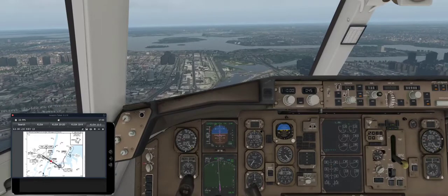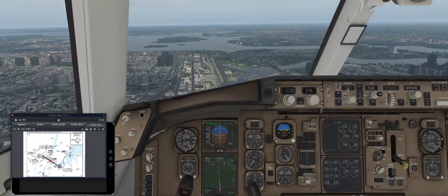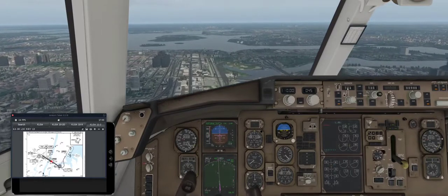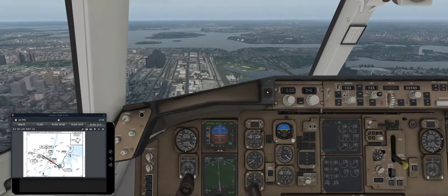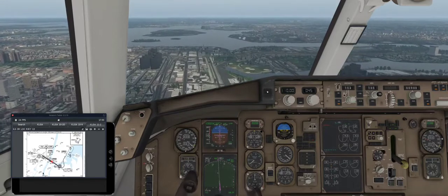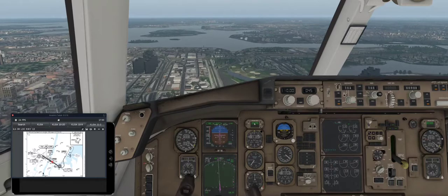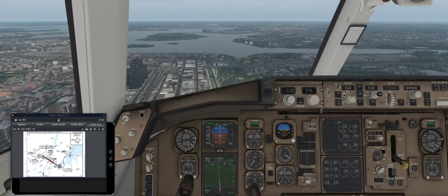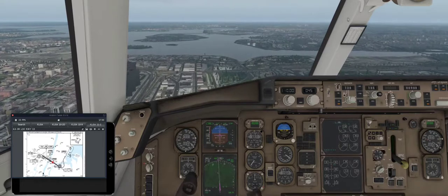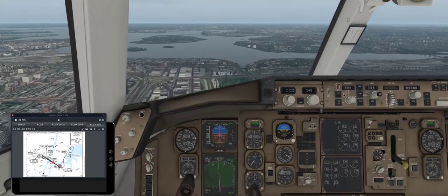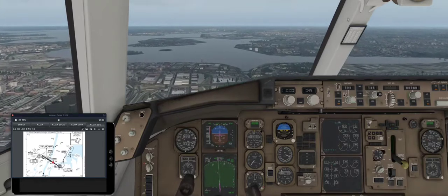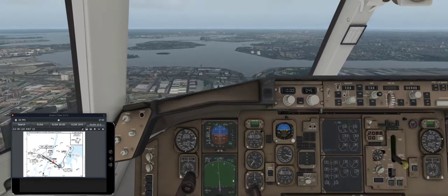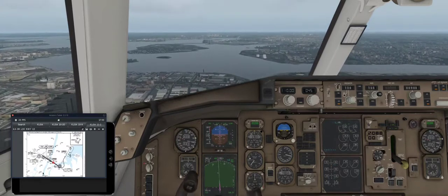Oh, I don't have full flaps out. We overspeed the flaps just momentarily. Our autoland 3 is on, that's good. Here we just got control. 1,000. So we're selecting 120, which is an appropriate airspeed. It's following the glide slope, it's following the localizer.